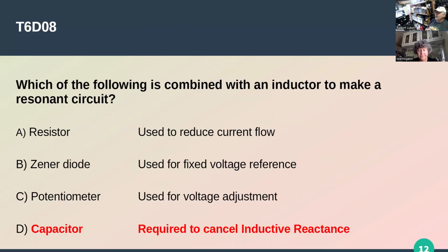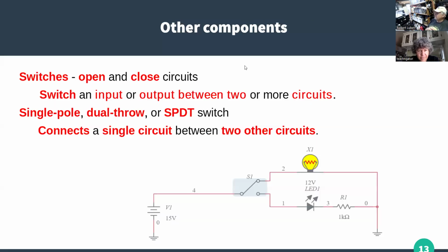Okay. LC circuits are just that, LC, inductor and capacitor. So any inductor and capacitor, either in series or parallel, will have a resonant frequency at some point, depending on their values. And sometimes we don't want those resonant points and have to do things to fix it.